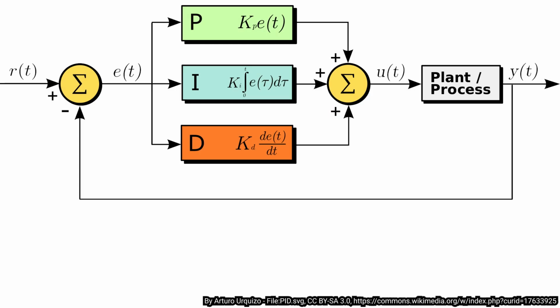The most popular solution, according to my experience right now, is to use a PID controller to control the system. PID stands for Proportional Integral Derivative controller, and the distinguishing feature of such a controller is the ability to use these three control terms to apply accurate and optimal control. The block diagram shows the principles of how these terms are generated and applied.